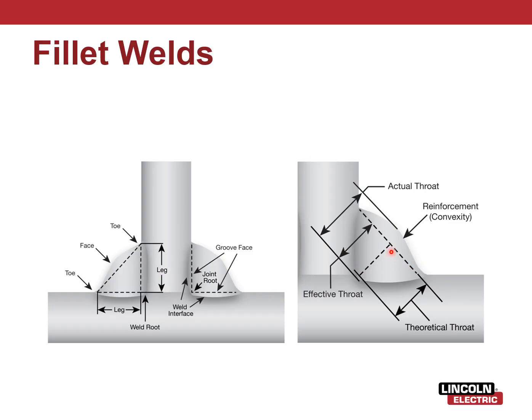Okay, over here we've got some more technical information for the weld profile. From the face of the weld to the farthest point of penetration in the root is called the actual throat. So that's basically the widest point between the cross section of your weld material. Okay, the effective throat: you're going to take a cut across the shortest distance from toe to toe.